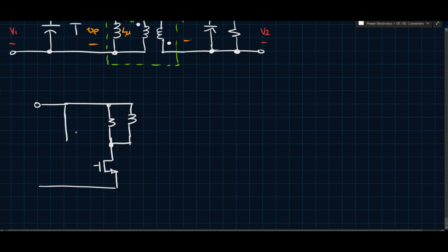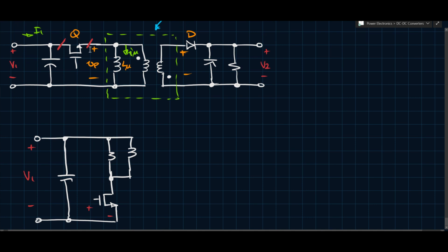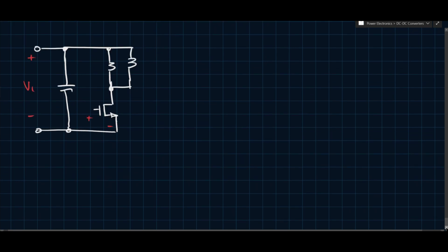And so the transistor is now connected here, relative to the negative rail. So when you're applying a voltage to the gate, you have to ensure that VGS is greater than a certain value, whatever that value may be for that transistor. It's much more straightforward to ensure that this voltage is whatever it should be than it is to ensure that this voltage up here is. So this is a much more straightforward, simpler, and more stable way of gate driving.